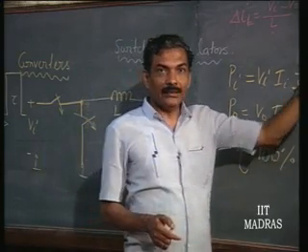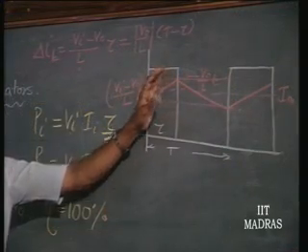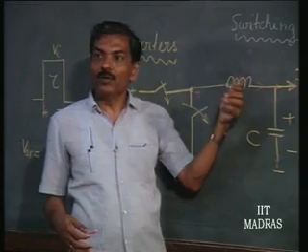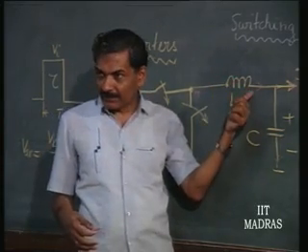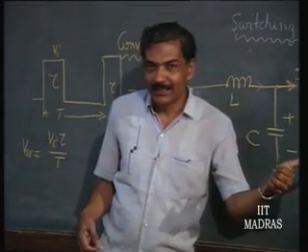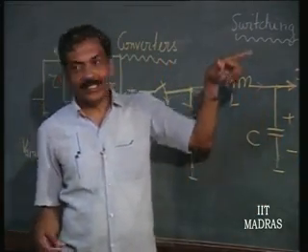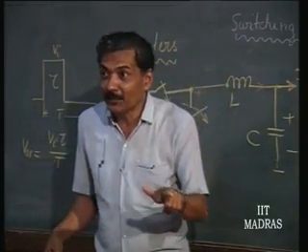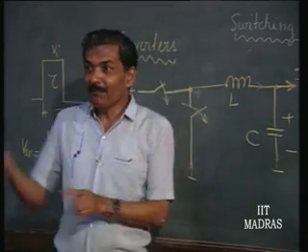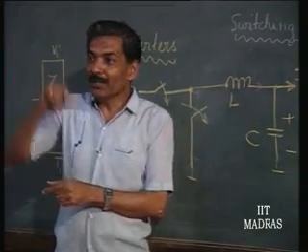So, this current is going to be flowing into what? Let us again see, this is how engineers must do approximations and arrive at sensible ideas in design. This current comprises both the DC current and the change in current. The DC current will flow into the resistor, and the AC current, that change in current, will flow entirely, if you have done a good design, into the capacitor, and develop a voltage dependent upon what the current is.